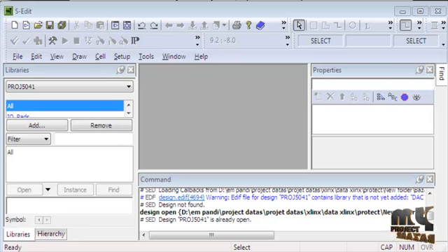The data reconstruction block is reconstructed by using the MUX block. It has 2 inputs and 1 selection line as the input. In this data reconstruction, 6 MUX blocks are used, and the output of the data reconstruction block is given as input to the CML flip-flop, and that flip-flop is used to divide into MSB and LSB bits.